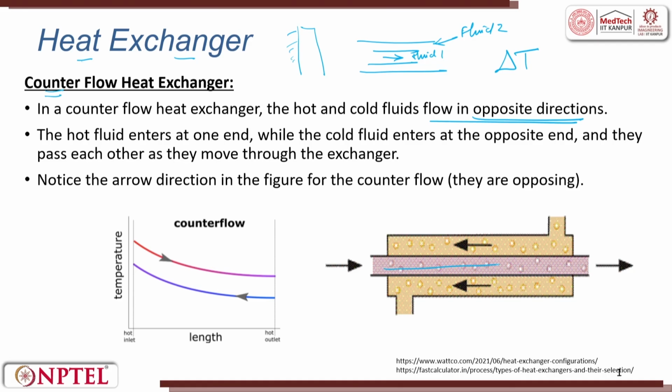So, this one fluid flows here, the other fluid flows here. If the delta T is very small, then exchange takes a longer time. Generally, what we do is we try to reduce the temperature here and try to send a hot one here, but there also you can't have a steep dT. So, there has to be a small constraint on this. The dT need not be small, but it has to be within a range.